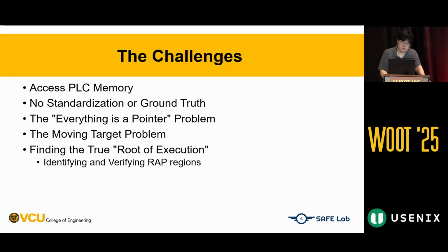So to dive into the PLC's memory, there are a few challenges. First is the fundamental problem. PLC's memory has no rules. Unlike a normal computer, PLC memory has no standards, no documentation, no memory layout announcement. Every vendor uses their own proprietary format, including their proprietary protocols embedded in the industrial protocols.